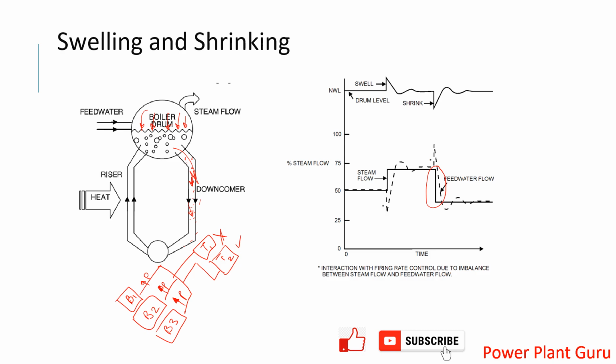So that will also be a temporary phenomenon which will cause your levels to go low. The pressure is also pushing the water to go down, as well as these bubbles which are here everywhere, that will also go smaller, and then this will also push that water into this area, and then your drum water level will go down. That's what you can see. As you are reducing the flow, the pressure will go high, which will try to reduce your level. This is a temporary situation.